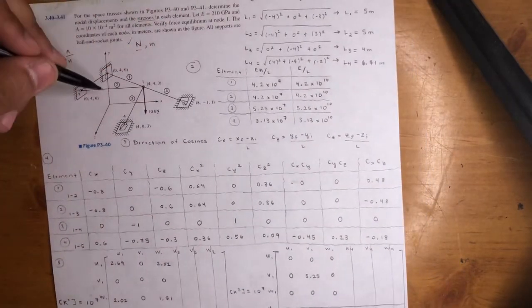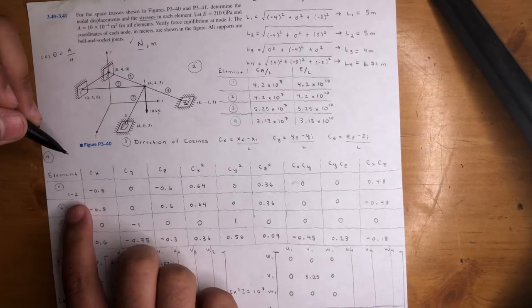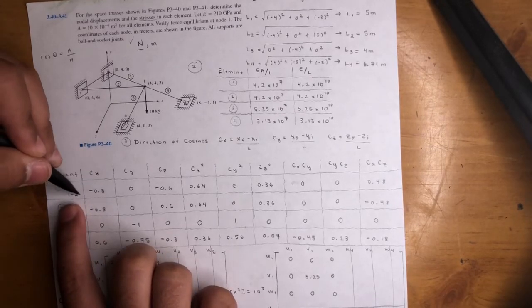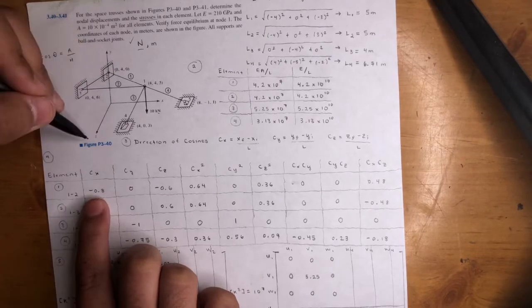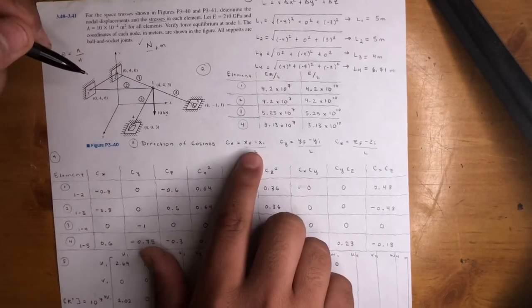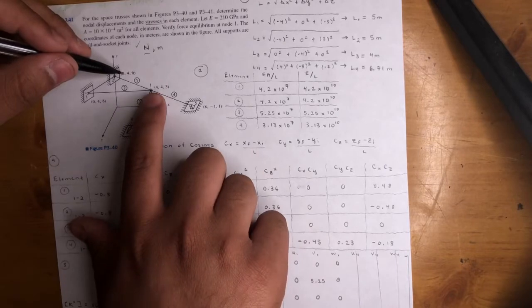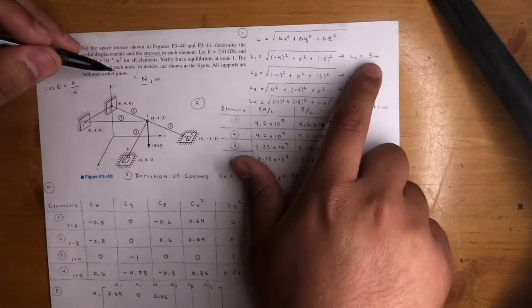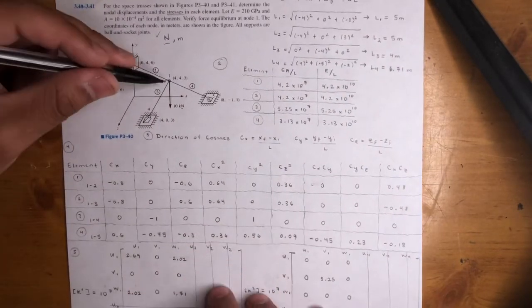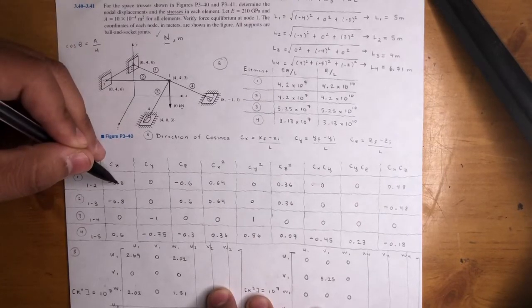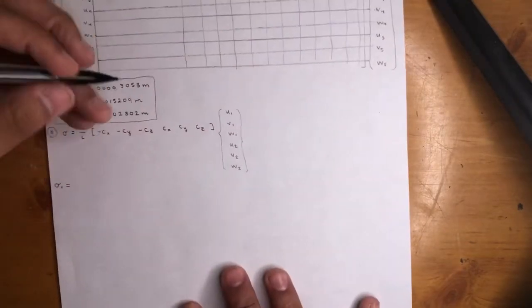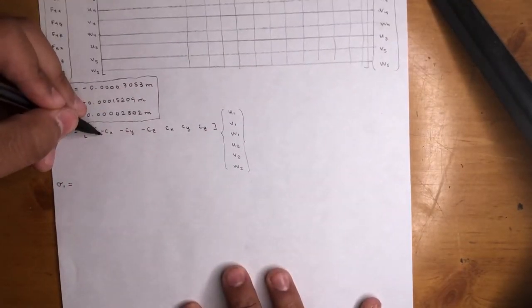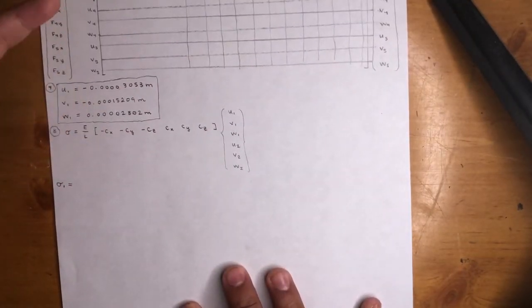Now, if you remember, I told you that the signs, it's really important the way you determine direction. Because in this case, we went from 1 to 2, right? So we did 2 coordinates minus 1 coordinates, right? That was a negative. Let's do the first one again. XF minus XI. It was 0 minus 4, which is negative 4 divided by 5. That's a negative 0.8. If you would have done the other way, that would have been a positive 0.8, okay? And if that would have been a positive, that would have switched this sign right here. It would have been a negative 0.8, and that would have given you a tension or compression value.